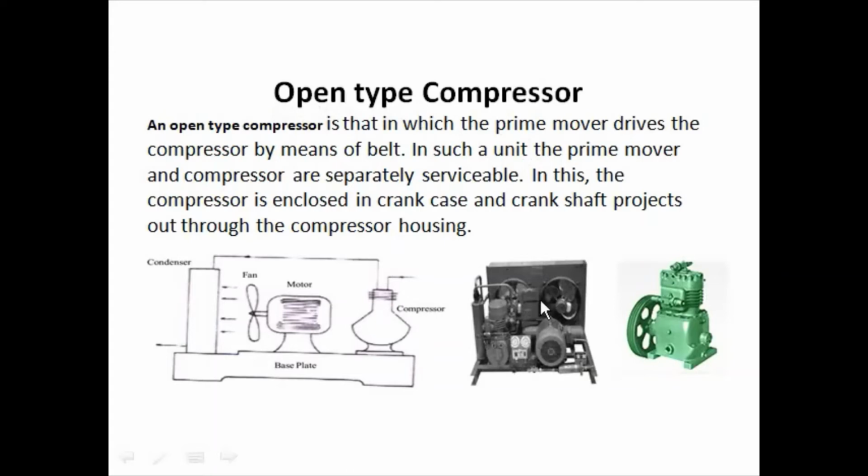As you see, this is a motor, and this is a pulley which has to be connected to the motor so as to drive the compressor. This construction here shows the separation of the components. This is the compressor, and this is the motor. The motor has to drive this compressor in order to allow the compressor to suck and to create the flow of the refrigerant.